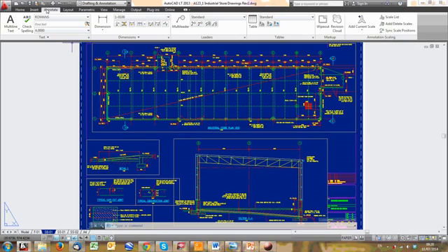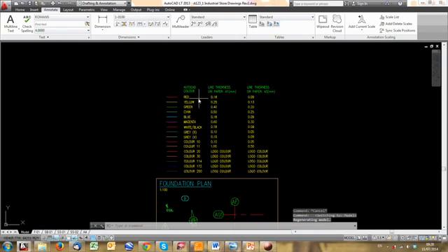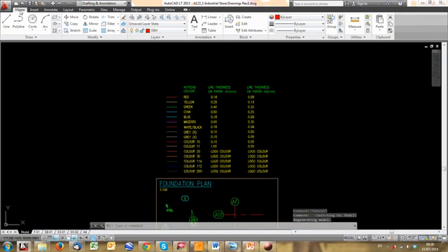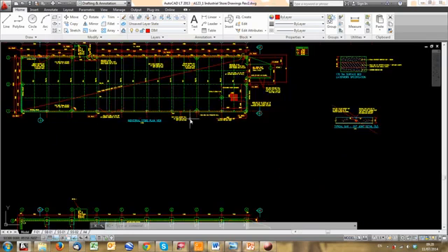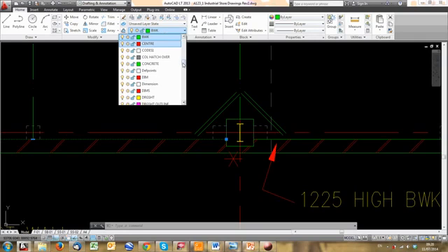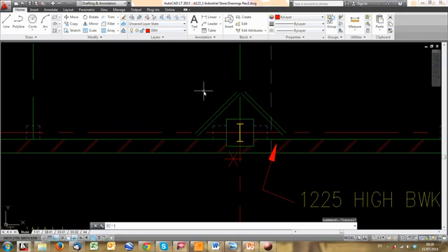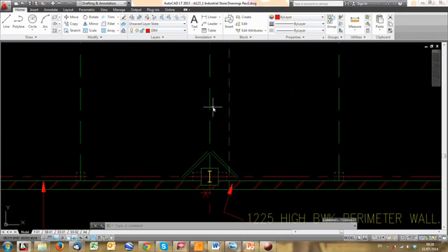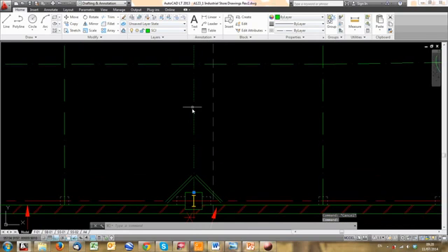Just one thing I forgot now with those layers and colors. I'm going to go back into model space. Those layers are set here. So if I click on something, this corresponds to, for instance, brickwork, BWK. If I'm looking in my layer state here, I've got a list of all sorts of different layers. And each layer has a color and a style, and that color obviously is associated with something. And you can also associate the layer with a particular type of line. You'll see this is a dashed line.